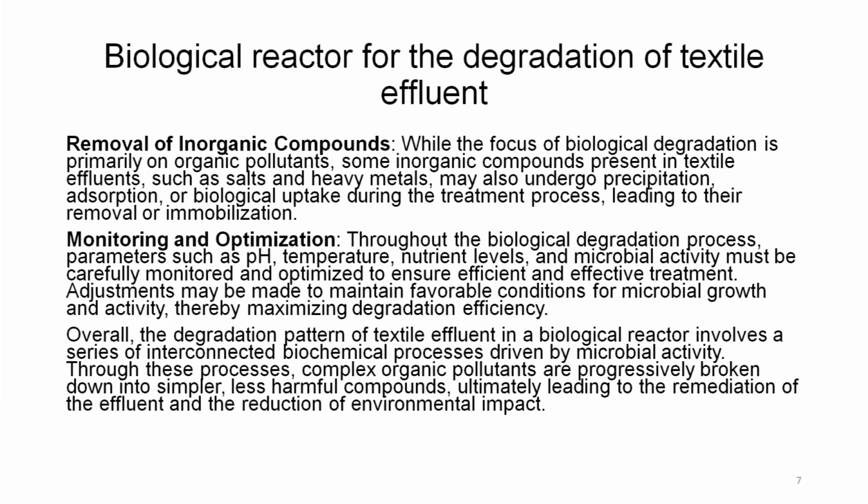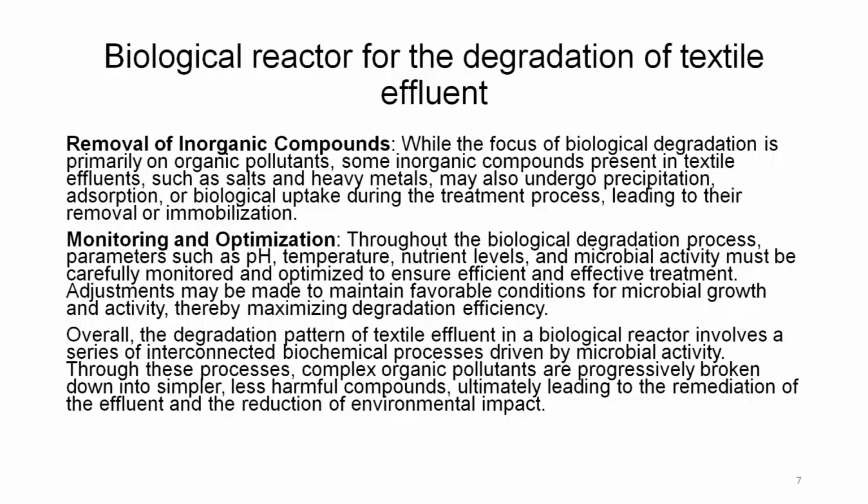Now, this is very important. If the microbes are not thriving properly, if they are not growing properly due to adverse pH or temperature conditions, then the enzymes present in the three different types of bacteria will be affected, their colonies will die out. If they die out, then neither acidogenesis nor acetogenesis nor methanogenesis will take place. Therefore, their optimization is very essential.